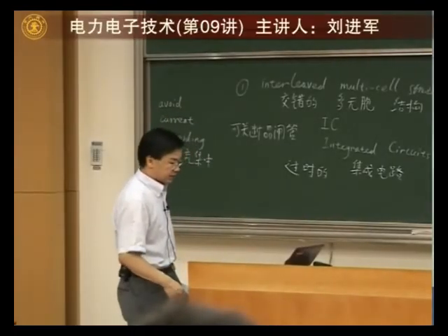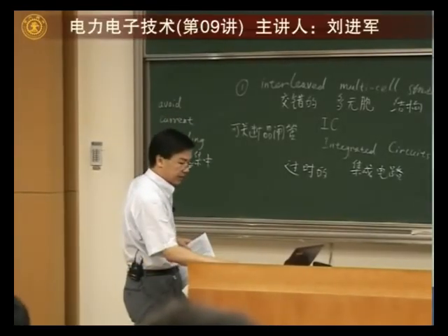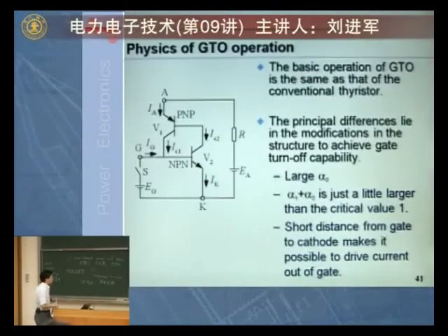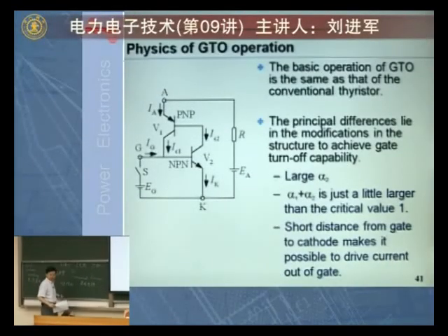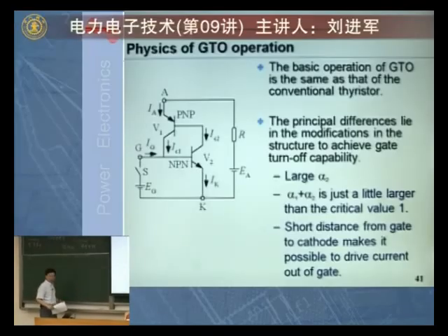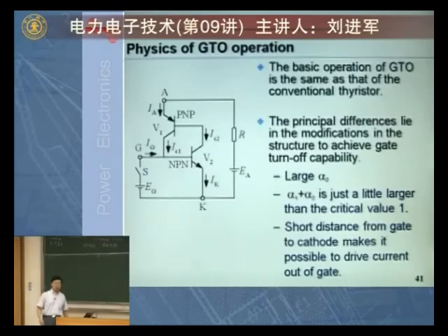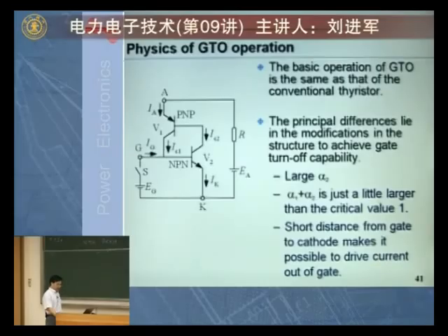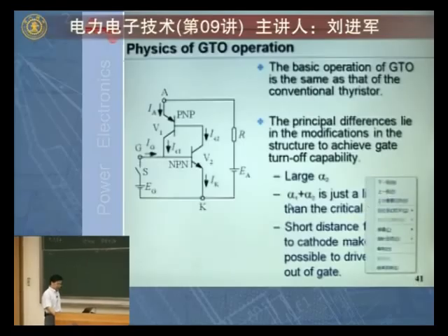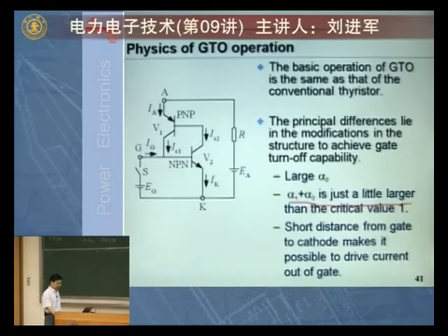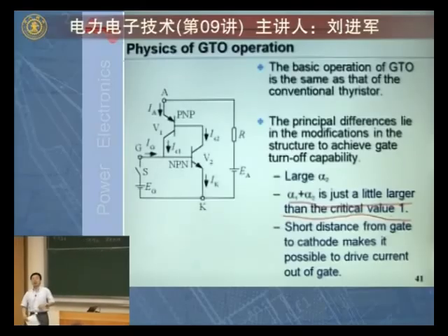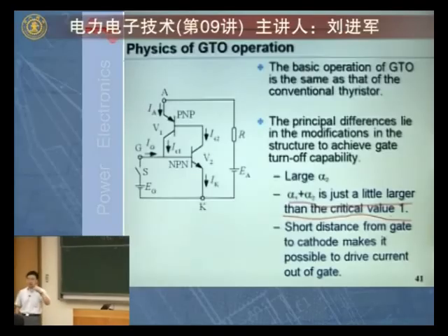There are other differences. I will mention them in the next slide. The other difference is usually when we manufacture this thyristor, we intentionally control the coefficient of these two transistors.